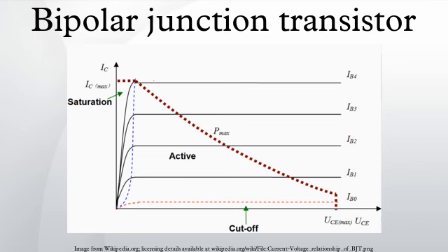Because most BJTs are designed to maximize current gain in forward active mode, the current gain in inverted mode is several times smaller. This transistor mode is seldom used, usually being considered only for fail-safe conditions and some types of bipolar logic. The reverse bias breakdown voltage to the base may be an order of magnitude lower in this region.